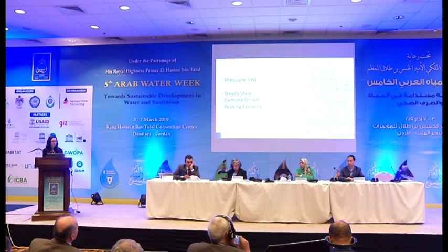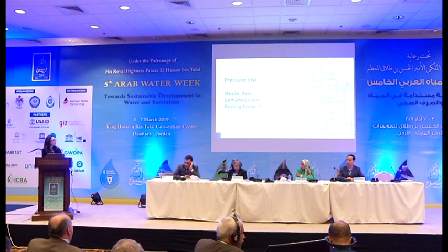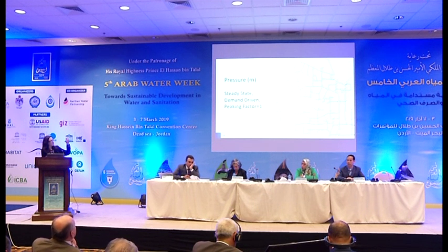So if we are using a peaking factor of 1, we can see that those people who are on high areas are still suffering from low pressures compared to the people on low areas who have high pressures. The pressure ranges between red up to green. The red shows low pressures, the green shows higher pressures.